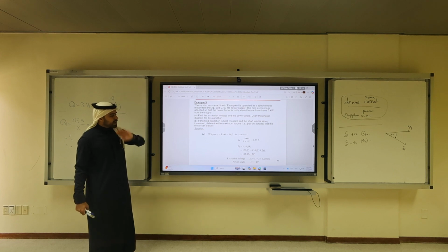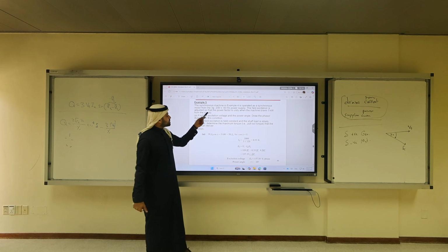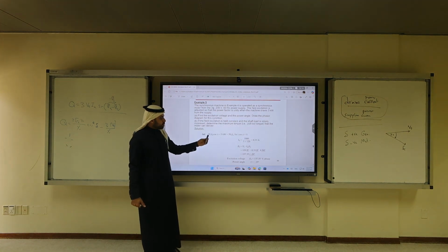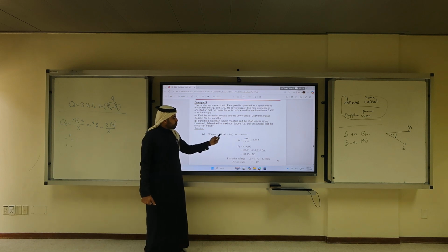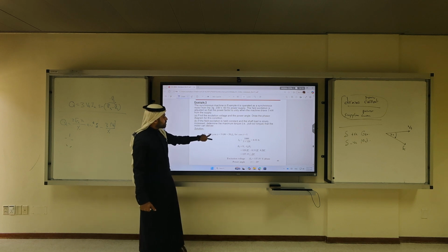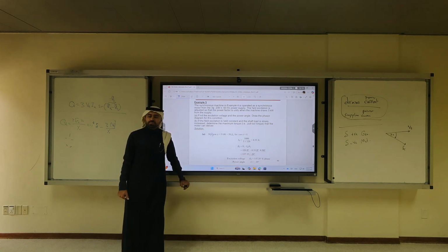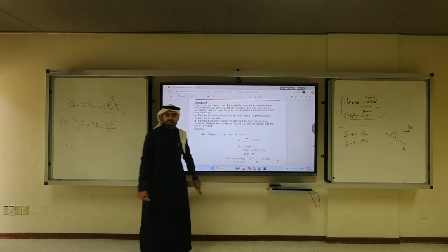So this is very important, okay? So it draws 3 kilowatt from the supply. Find the excitation voltage and the power angle. So here what did we do? We have cosine theta is 1. We know the real power, 3 kilowatt. We know VT. What do you need to calculate? IA. You calculate the magnitude of IA. So the magnitude of IA is 3,000 over 3 times 120.